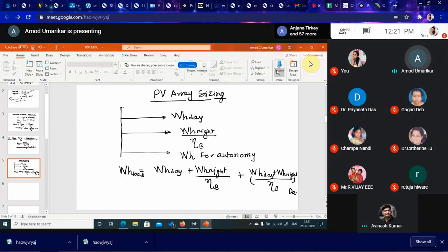So what we have to do is this part particularly. For days of autonomy, the battery will complete the supply, so we have to replenish the charge or recharge the batteries again. So we'll divide that replenishing of charge over a number of days rather than one day.